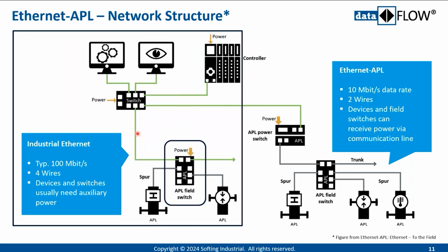You have here the connectivity to the north. That's this one here. On top it can be a cable, like a typical Ethernet cable would be copper, would be 100 meters. If you have a longer distance, for this one here, 2 to 3 kilometers would be the fiber channel. And here the spurs we're talking about actually to the south are 200 meters.